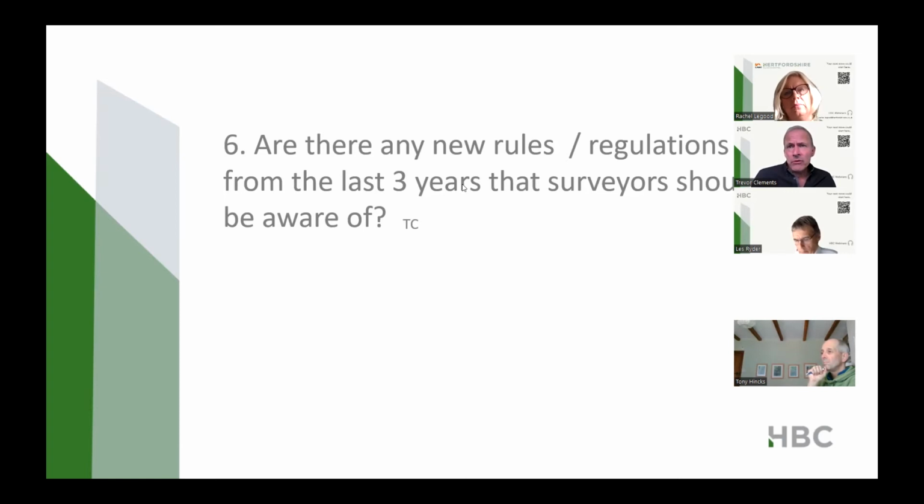And most recently, we've got these new amendments, some of which, well, we had a change coming in June of this year, where cavity trays have got an amnesty from the requirements to be non-combustible in high-rise residential buildings, and also on the back of the same legislation, December 22, we've got some new requirements coming in, mainly to do with the combustibility of the facades of buildings and changes to buildings over 11 metres, not to bring them up to the same standard as residential buildings over 18 metres, where the whole fabric of the external walls has to be non-combustible, but certainly the external surfaces have to be non-combustible.